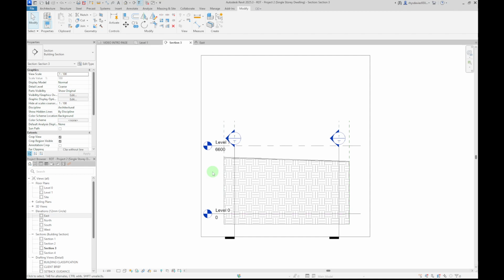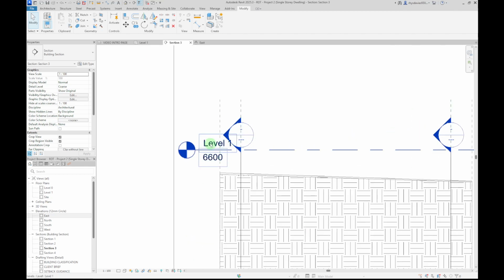That's really handy. This happens a lot in Revit. You can create new levels, and they may not be visible initially. Once you find them in one view, maximize the 3D extents and you'll be able to see them everywhere. So that's part 1 of the lesson.